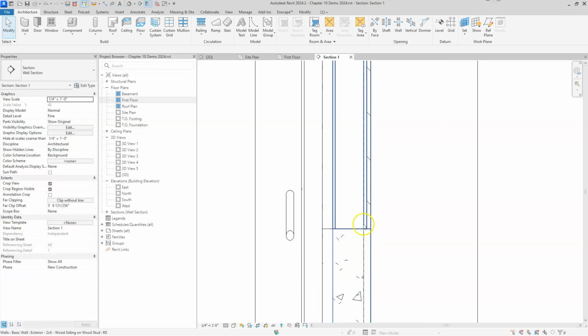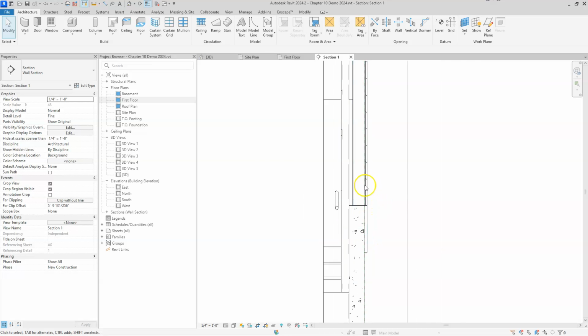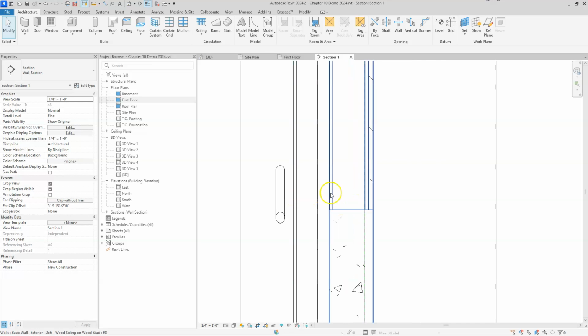So when you think about the floor that is going to be suspended on the foundation wall, that would be sort of like the main floor. That floor is going to sit on the foundation wall, but it's going to run out to and stop at that same magic line, where that reference plane is. Okay, so keep that in mind as we're creating the floor, paying extra special attention to the boundary of that floor and where it runs.